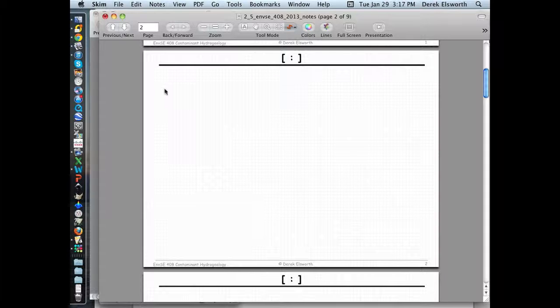It allows us to take a core, and, well, actually perhaps now is the time to do the example. Right? And you take a core, and I think assignment number 4 for you is exactly to do this, and say that if you had piezometers on this core, you'd have some fluid levels which are present in this to some height, H1 here and H2 here.